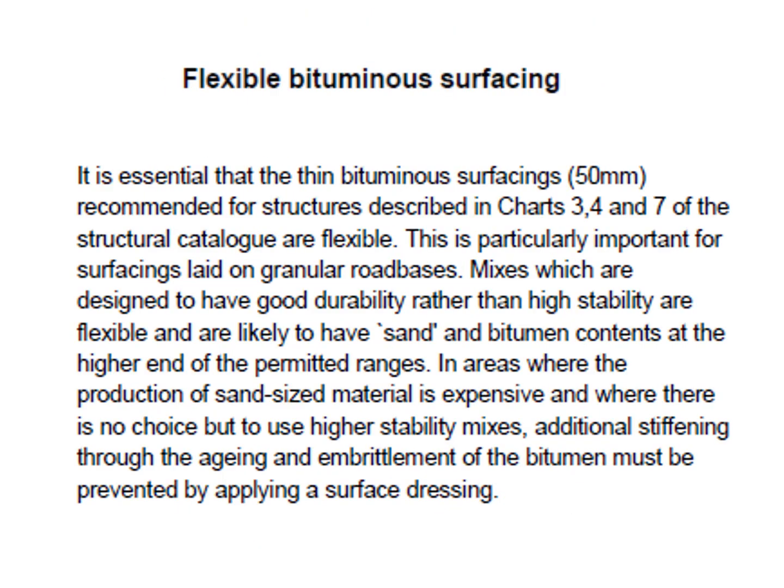Then the next stage for the surfacing is the flexible bituminous surfacing, or you can say the pre-mixed bituminous material which is being used at the top. It is essential that the thin bituminous surfacings of 50 mm recommended for structures described in charts 3, 4 and 7 of the structure catalog are flexible.